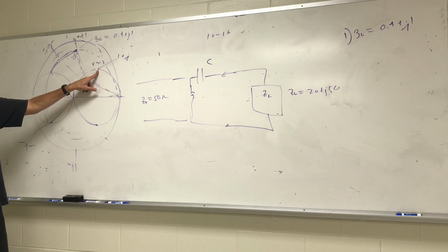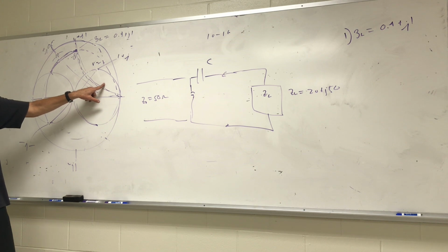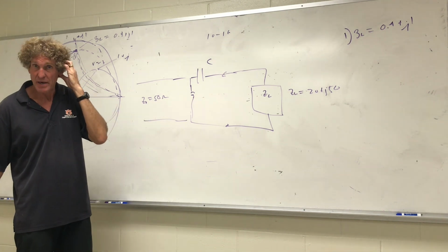Well, an inductor has an impedance of plus J omega L, right? Normalized, it's plus J omega L over Z naught, right? That is called impedance. 1 over impedance is admittance, right? And it would have minus J. We need to have minus J. That's why there would be an inductor there.